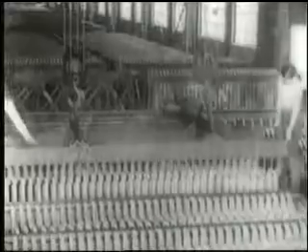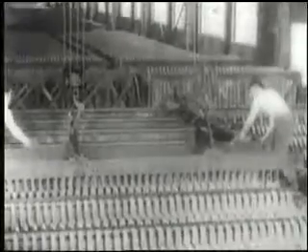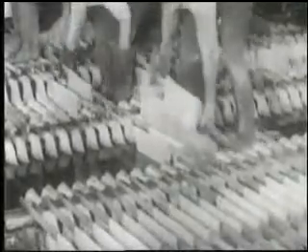Here's another, rectification for electroplating operations of all kinds, operations possible only with direct current. Still another example, furnishing DC in steel mills for the driving of variable speed motors, such as the one controlling this giant ladle, or the ones driving steel conveyors with such precise control of speeds that danger of buckling and tearing and consequent mill damage is eliminated.